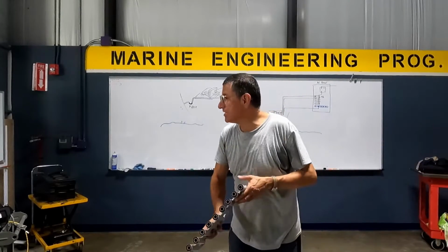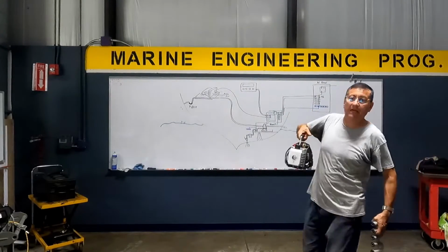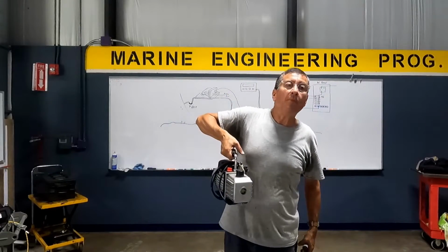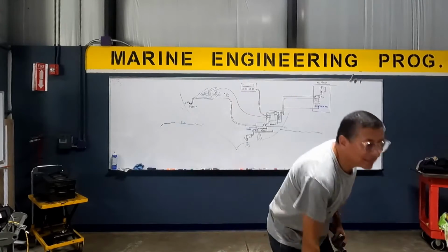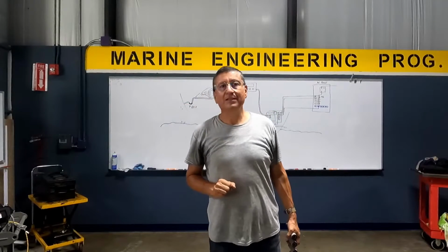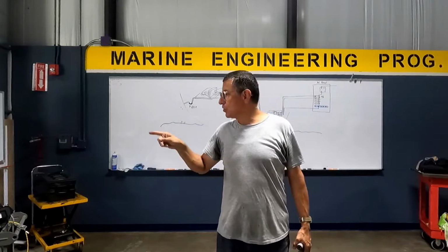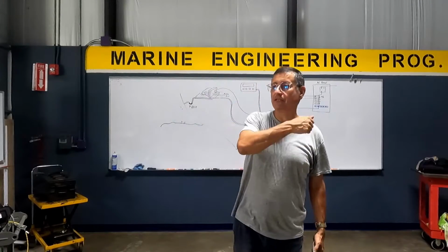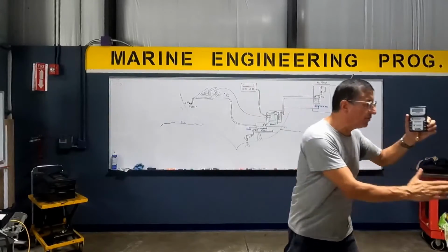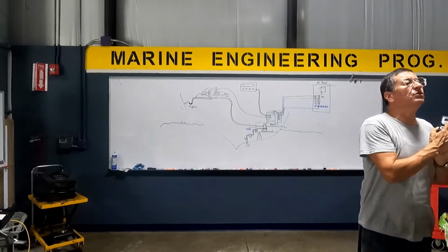Okay. And it's with this pump. I'm going to explain the process. In the videos I have that explanation in detail. And you operate that pump until the gauge reads around 500 microns. This is the moment where all the humidity was absorbed. You stop the pump and you connect the recovery machine and you recharge the system with the Freon again. It's not complicated, it's simple. I'm going to explain how to use the vacuum pump, how to connect the vacuum gauge, and the vacuum gauge normally starts at 2000 microns.